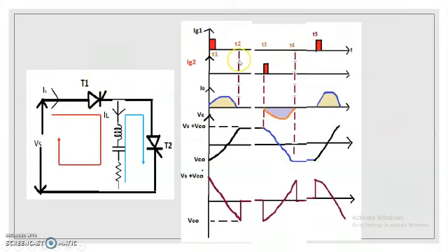So from the time instants we can understand that there is a time delay between turning on of one thyristor and turning on of the other thyristor. That is, between the time T1 to T2, thyristor T1 is on. And between the time T2 to T3, both thyristors are in the off state. And between the time period T3 to T4, T2 is turned on.